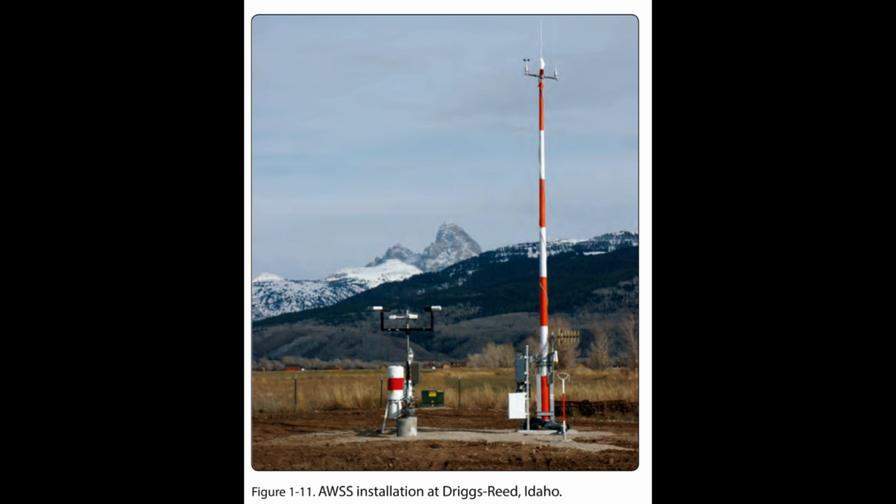Figure 1.11. AWOS and ASOS/AWSS offer a wide variety of capabilities and progressively broader weather reports. Automated systems typically transmit weather every 1 to 2 minutes, so the most up-to-date weather information is constantly broadcast. Basic AWOS includes only altimeter setting, wind speed, wind direction, temperature, and dew point information. More advanced systems, such as the ASOS/AWSS and AWOS-3, are able to provide additional information, such as wind speed, wind gust, wind direction, variable wind direction, temperature, dew point, altimeter setting, and density altitude.